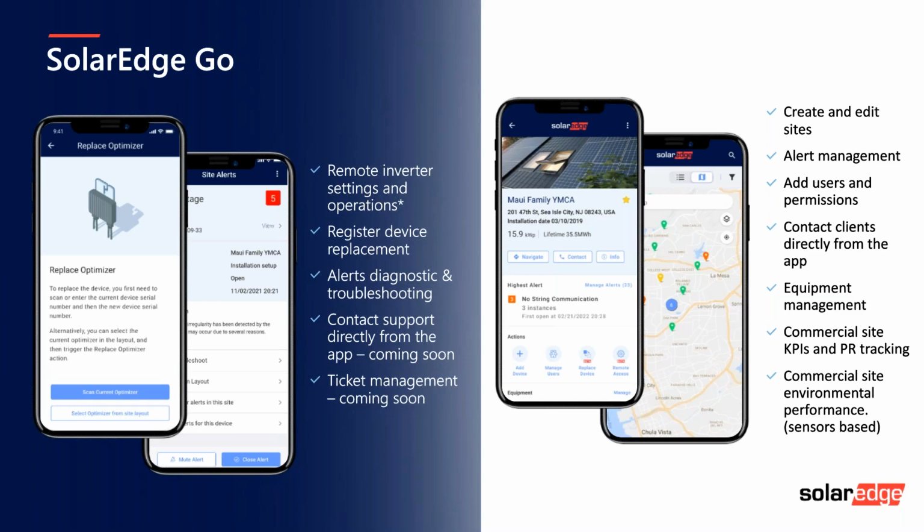So if you just think about that practically, you can install the system, set it up to do the firmware updates, and leave site. You can then that night or the next morning jump back into the system and finish off the commissioning, because sometimes firmware updates might take half an hour, 45 minutes or whatever, and you just want to get off, or it could be the end of the day and there isn't enough PV generation to kick in all the optimizers to do the pairing. So it is an absolute game changer for us, SolarEdge Go.